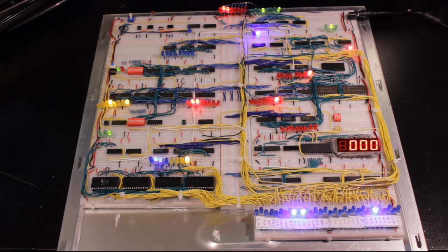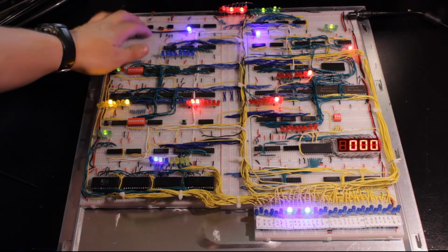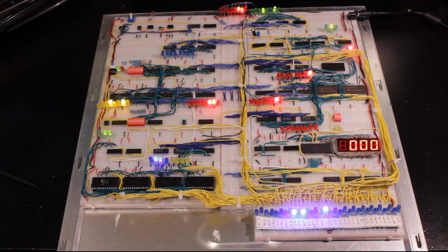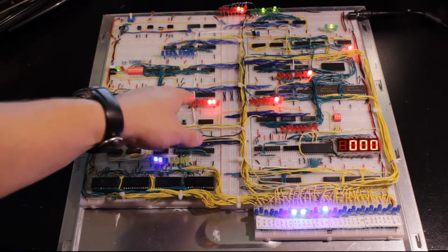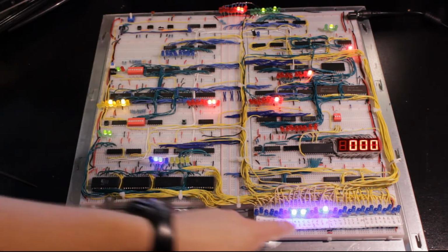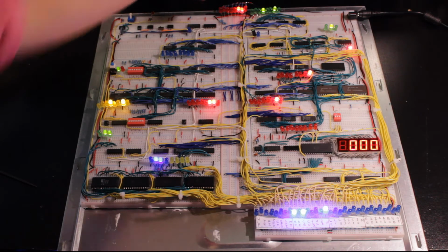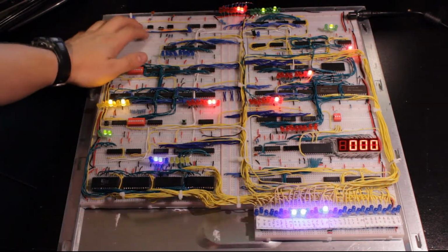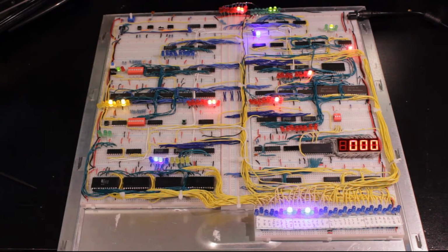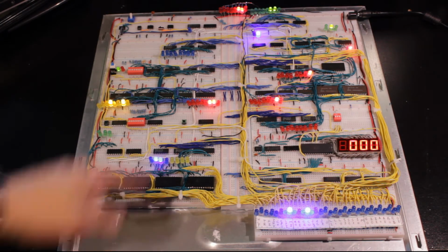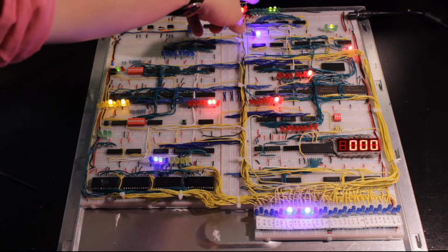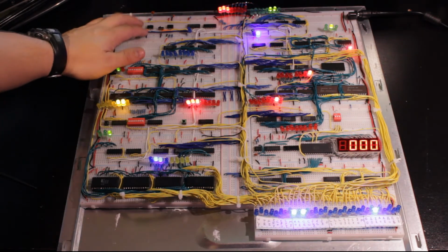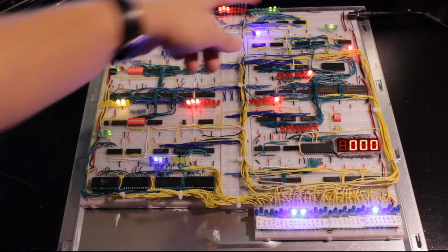0x60 for unconditional jump, so we're going to jump no matter what. This fetches the next location in memory. It's using this as a pointer to decide where to continue execution. So this value here is going to go RAM out onto the bus. We can see the jump signal is high, so this is going to go into the counter, and the counter is also enabled. So here we go. Boom, we've jumped to address 60, and we're going to take from the counter now, memory and counter out on the next fetch cycle because we reset. And we fetch that instruction, which again was 0xE0 for output A.